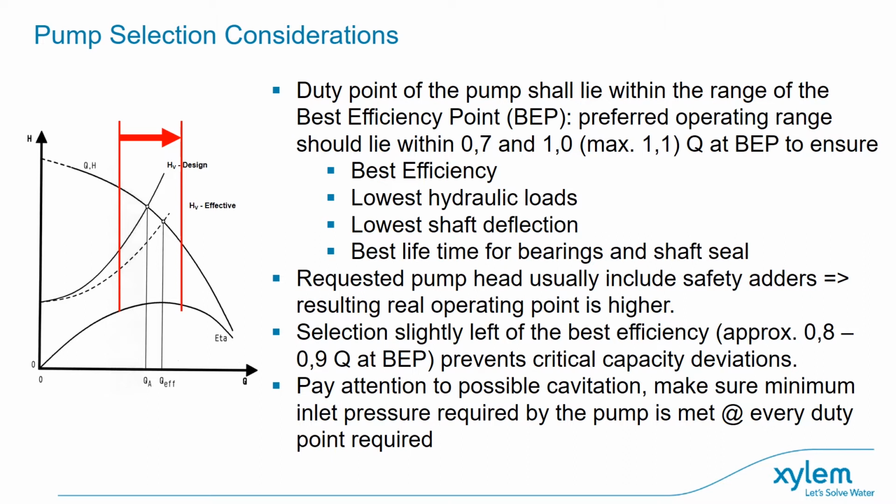because this can reduce the flow through the pump, obviously, which can create higher working temperatures and can also create cavitation within the pump. The same goes if the pump is working too far to the right-hand side of the curve, where again you can get cavitation within the pump, which will quite rapidly reduce the pump life.